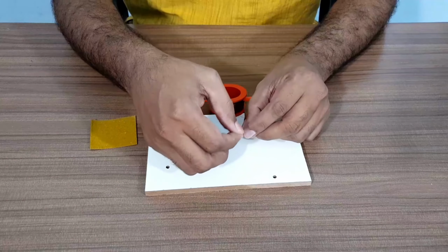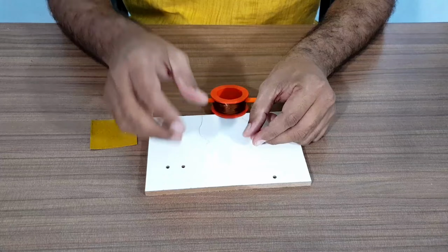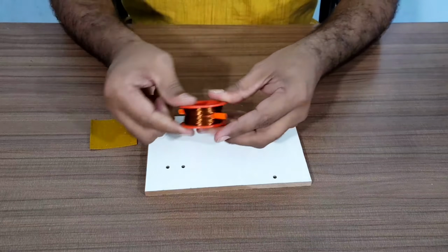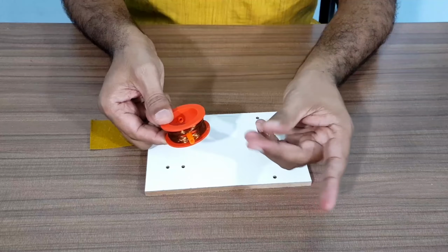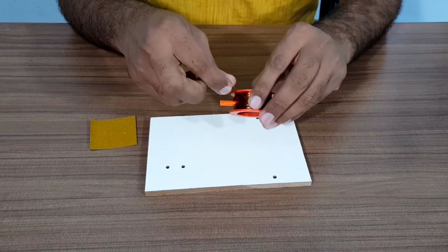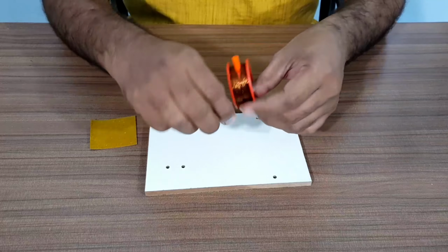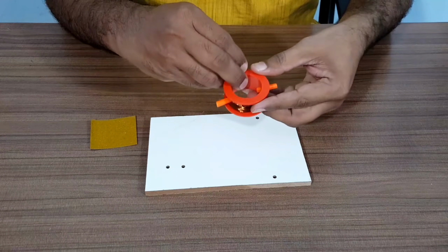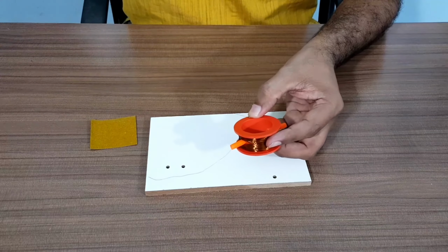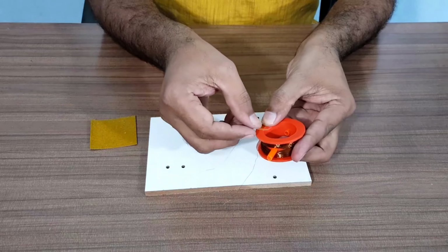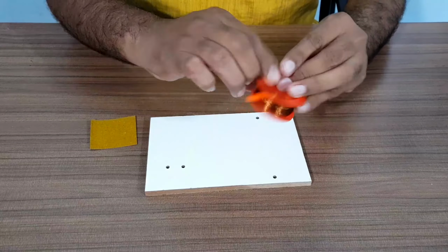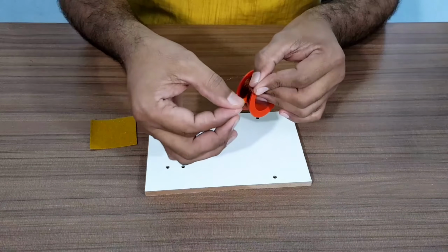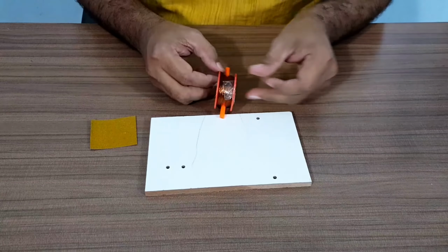We have to remove coating from the wires, but before that, what you have to do: one end is actually locked. This is the starting end, so it is not coming out, but this free end might again come out. So what I am doing, you can use a sellotape and stick sellotape here so that this wire will not come out, and also you have to make sure that both the wires should not touch each other.